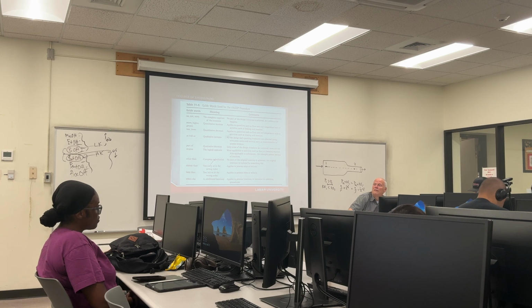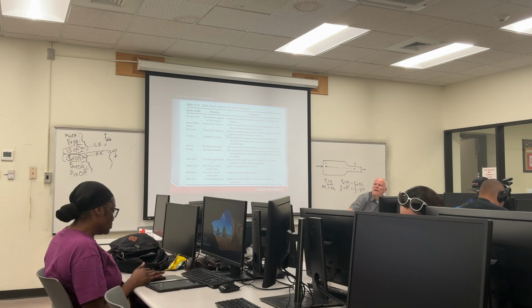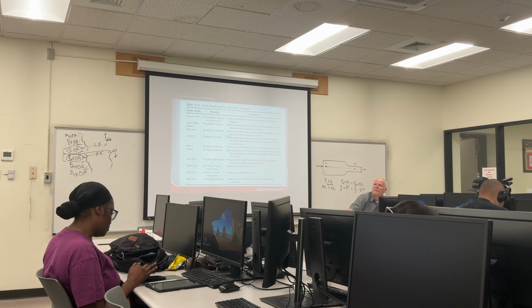What's the hazard? You lose your overhead condenser, and your tower over-pressures. Hopefully you have a relief valve on it, right? But overpressuring your tower is not a good thing. But that's a scenario. So then you go on to the next one: more, higher, greater.